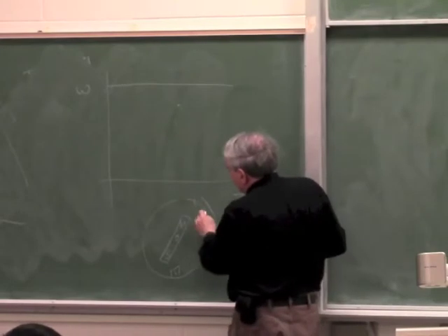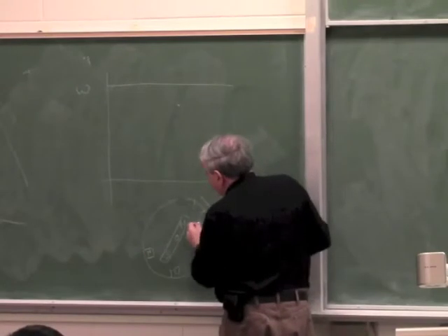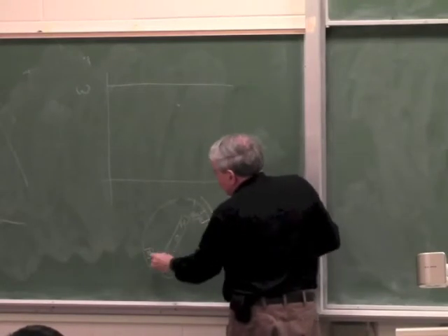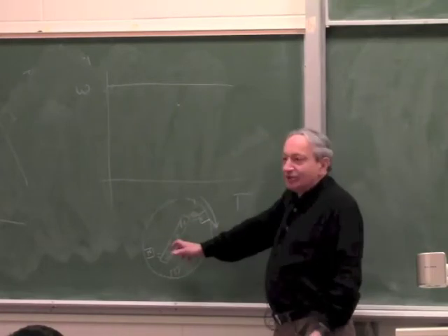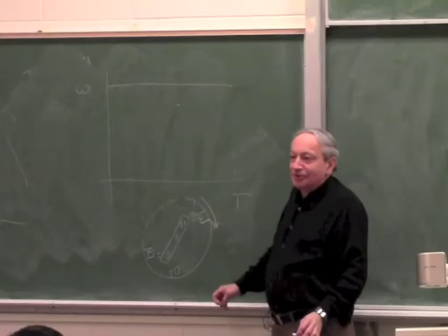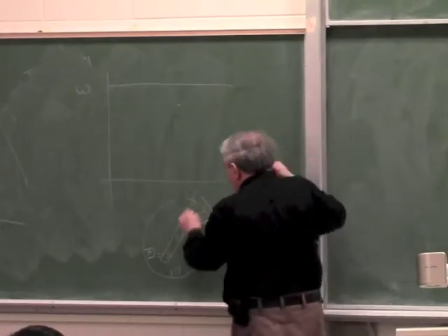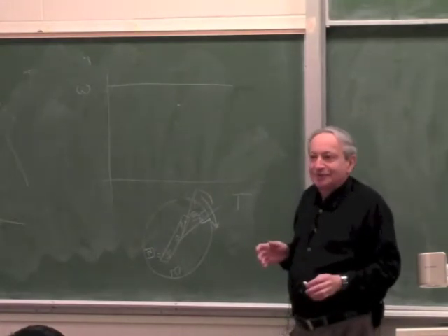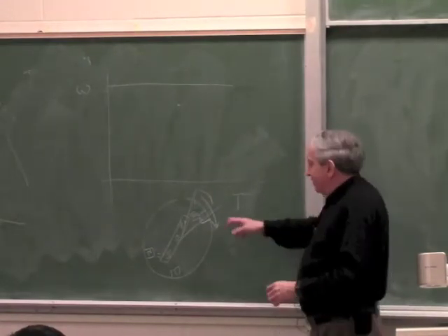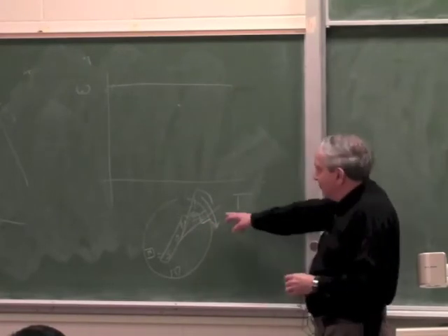So let's say if you have a bigger torque, the poles are like this, NS, and this is a magnetic attraction, but at some point, if you put more and more torque, it just breaks lock, and once it breaks lock, it loses all torque. Okay? And does somebody remember what this angle is called? It's only a week ago. Power angle, yeah. Okay? Sometimes it's called torque angle in some textbooks, but it's usually referred to as power angle.